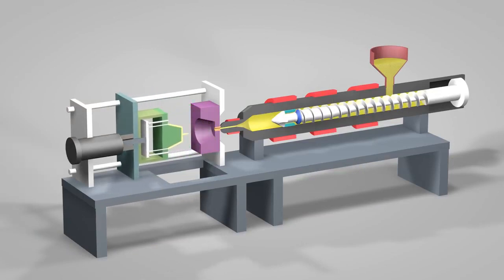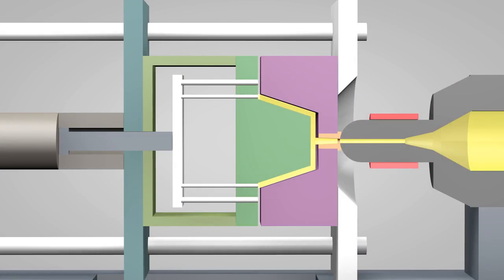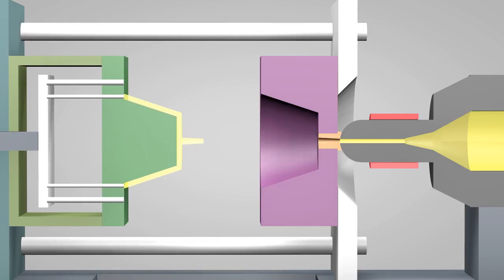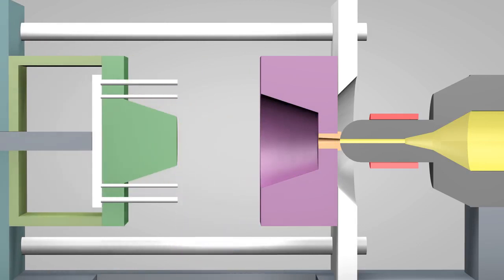As the mold opens, the volume increases without introducing air, which creates tremendous suction that holds the mold together. So at first, the mold slowly opens several millimeters to allow air to rush in and break the vacuum, and then the mold quickly opens the rest of the way so the part can be removed. These precision machined steel molds can cost hundreds of thousands of dollars.